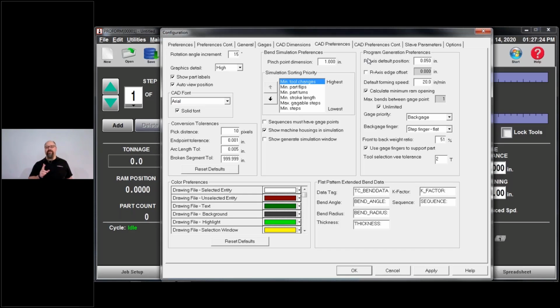What that means is when I am trying to generate an actual part, I'm going to generate simulations, and this is something we will see when we get into the software. I hit generate simulations. It's going to look at the profile for both the punch and the die, and see if the part actually interferes somewhere between where the punch comes in or where the die comes in.